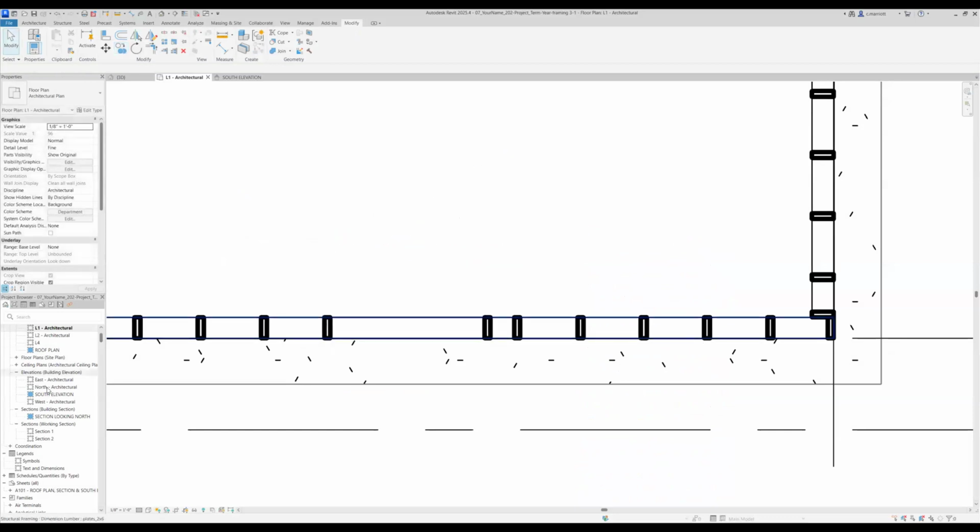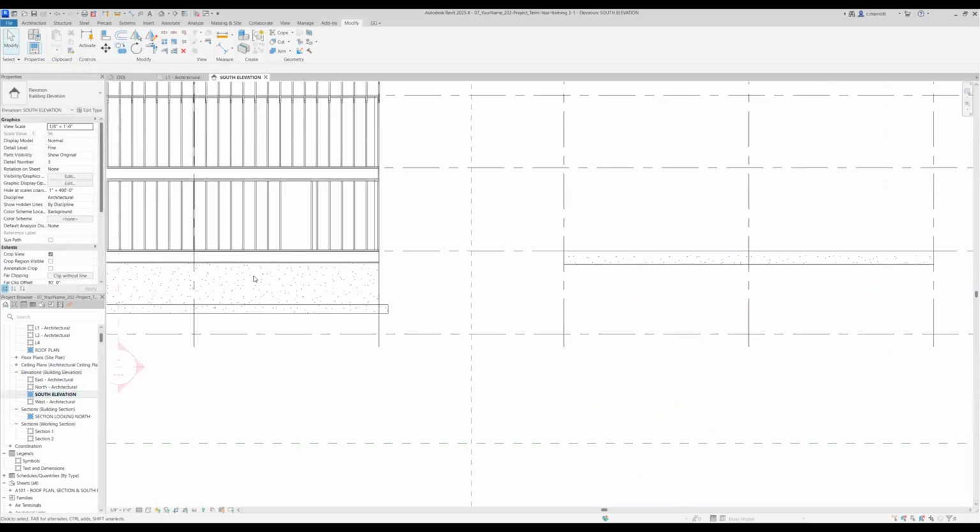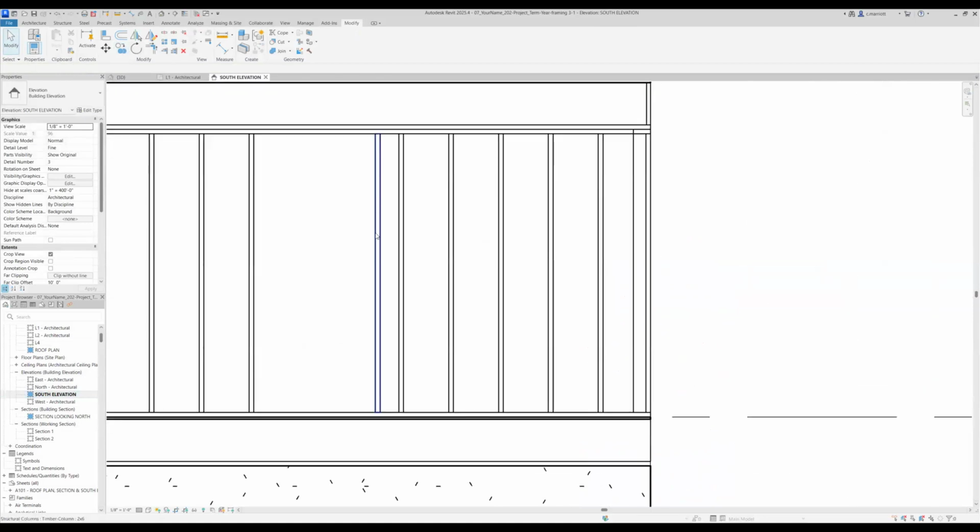Let's look at this in the south elevation. And there you can see there's this new stud created. Okay, so the space between here, though, is 3 feet 3 inches, because I'm going to have that 1.5 inch trimmer or jack stud and another 1.5 inch member here. But what I'll do before that is construct the header that's going to go into the file.